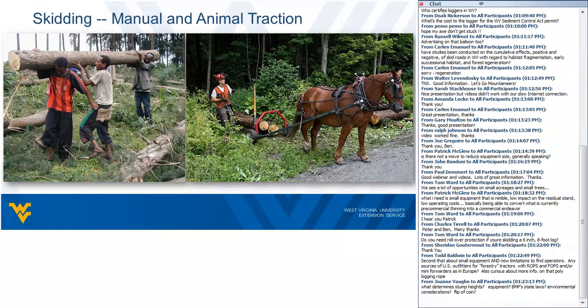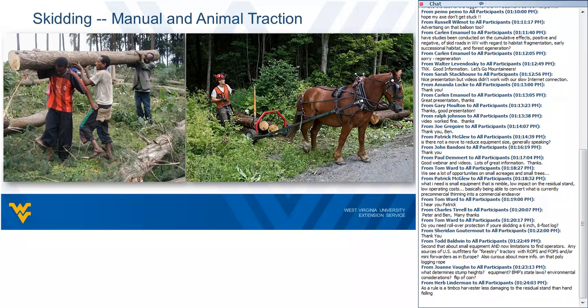Skid trails should be relatively safe and usable for continuing entries. That technology probably will not change dramatically in the next 50 to 100 years. But if you can plan to reuse them, that definitely is a very good practice to do, and should be encouraged whenever possible. And it doesn't take much effort at all to open those up. I mean, they're natural dirt surfaced or soil surfaced, so it's basically smoothing out the water bars and moving on,